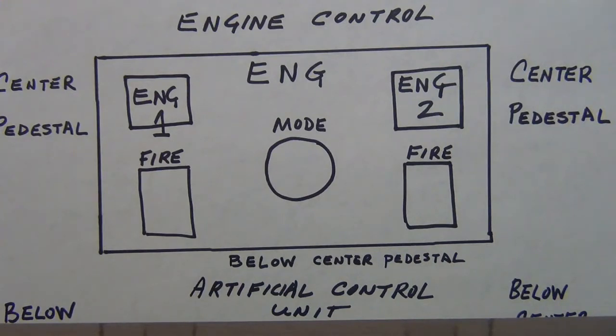Okay. Also, just be aware, kind of a side note, you have pack valves. If you have an engine master switch on, even if you're on manual start, if you push the button for manual start, by the way, both low pressure and high pressure fuel shutoff valves open. Remember? Or I said that. So yeah, just remember that, manual start.